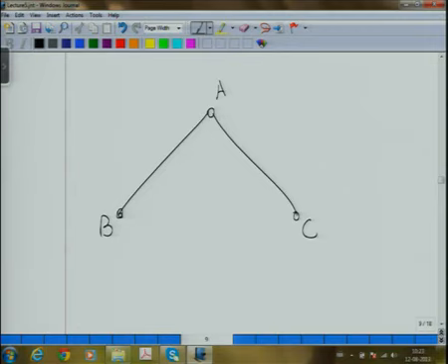Both of them have to be 0, because you could imagine AB is connected to another 0 force member which is in the same line. Similarly, AC is connected to another 0 force member which is in the same line.